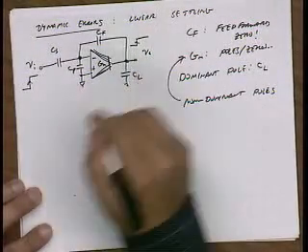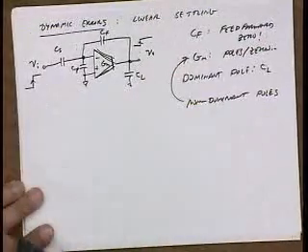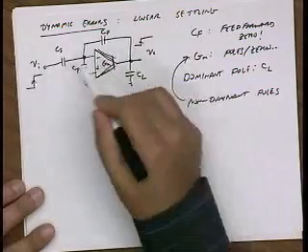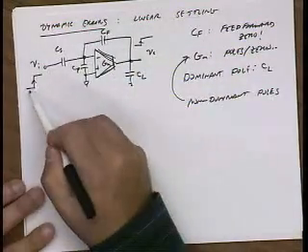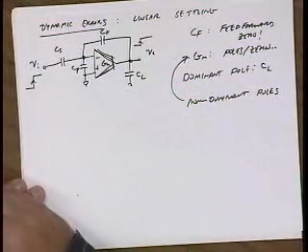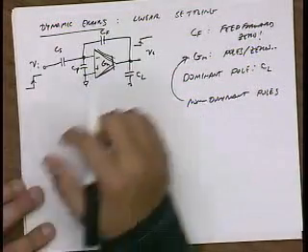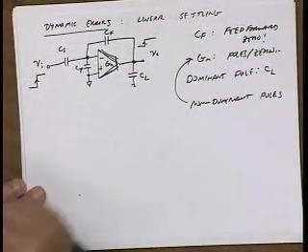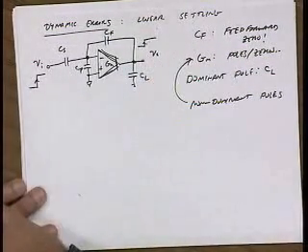With, let's say, a smaller magnitude. What determines the magnitude? Yeah, cap divider, right? So I've got this capacitive network. At the very instant of the step, because this amplifier has finite bandwidth, it can't do anything. So at that instant, the amplifier is not even there, and this is just a simple passive capacitive network. So I can calculate exactly what this step does.